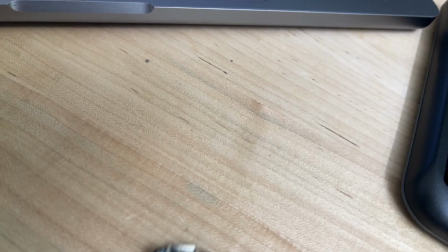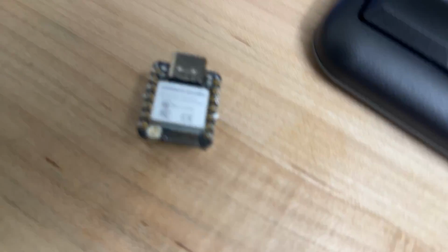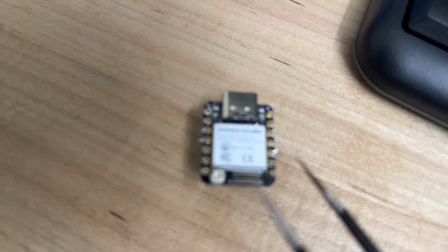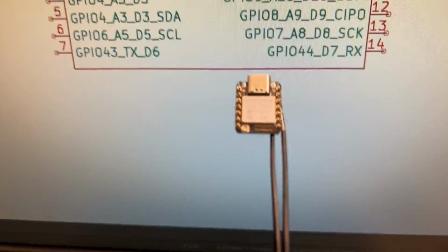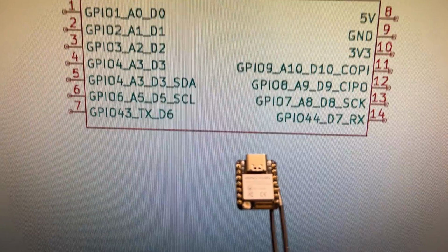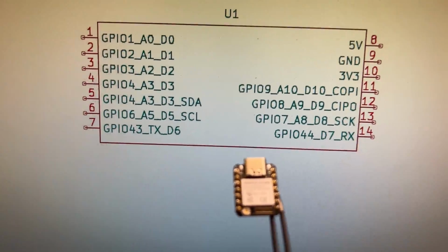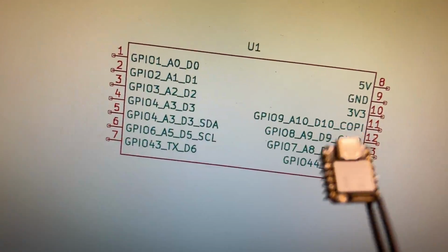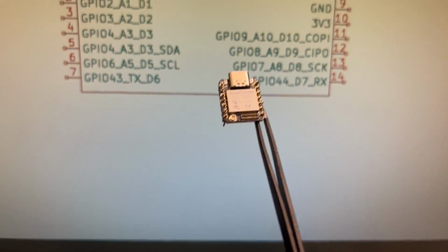As you can see, there should be 7 pins on either side of it, but even though their count is correct, they still don't match in size, which means this is an abstract view of your layouts, not a physical view, right?